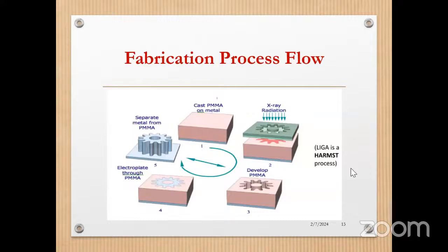So this is a fabrication process flow. I want a planar material, and this device has been fabricated. First I take a planar substrate material. I put a mask for the type of structures I want. I apply X-ray radiation to harden it. Then it is etched away using either wet etching or dry etching. In wet etching, I put some chemical solutions so that it gets etched away. Finally, the side regions are removed, and I get this PMMA material.